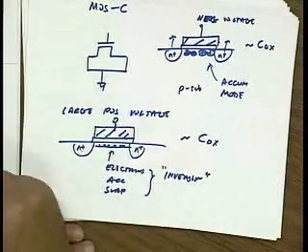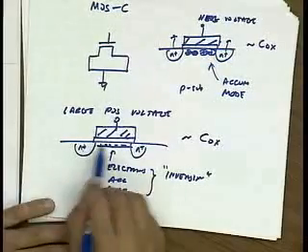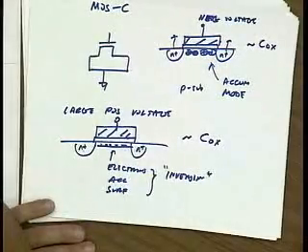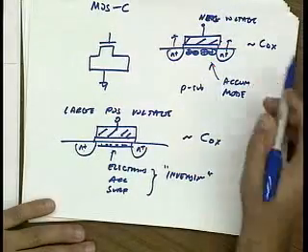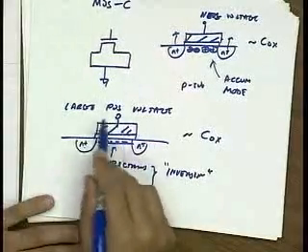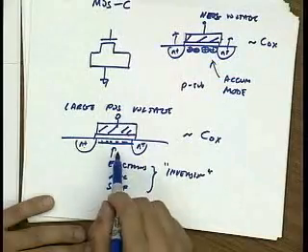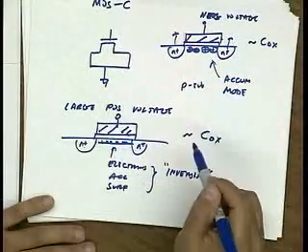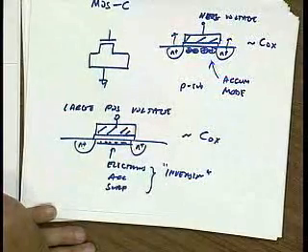Now, if you really want to get complicated, you could say, well, quantum mechanics says that charge doesn't quite accumulate at the surface. It's far away from the surface. Not that far away, but effectively, Tox just gets modified. And it gets complicated because depending on the voltage you put here, the Tox will vary. We'll come back to that point. But first order model is that the capacitance is just Cox, right? So that's not very interesting.